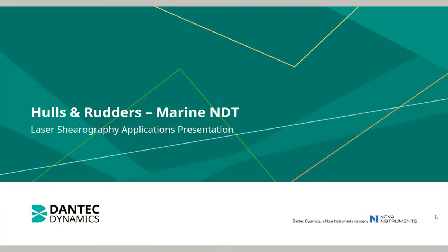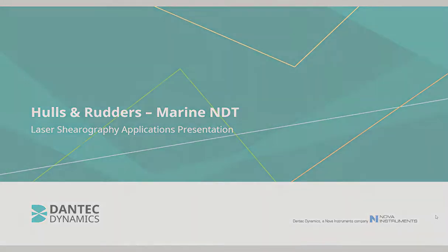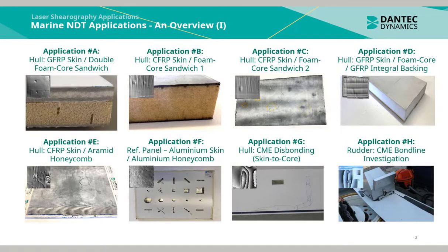This is an applications presentation of laser shearography being used in Marine NDT for the inspection of yacht hulls and rudders. Here is an overview of Marine NDT applications used with laser shearography. As can be seen, most applications are of sandwich or honeycomb components.